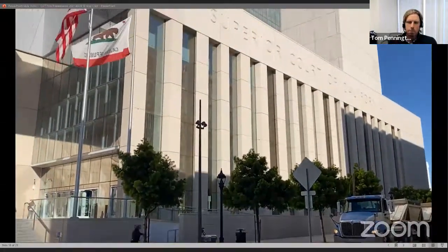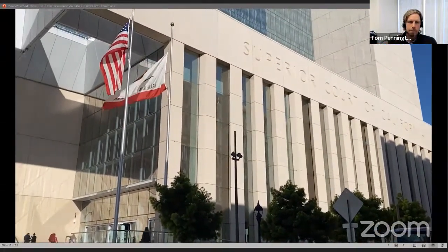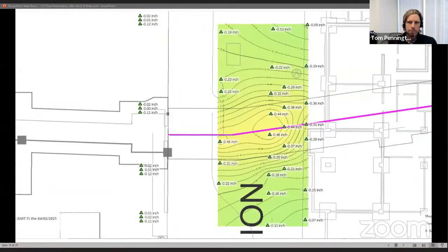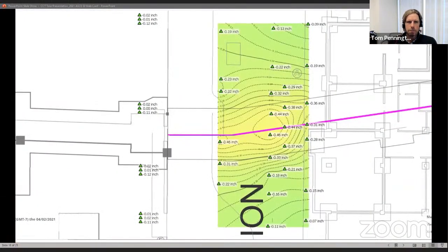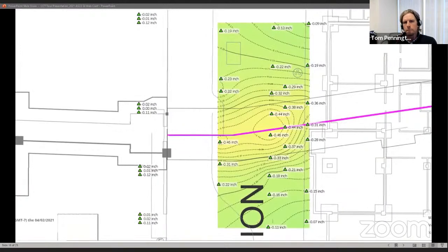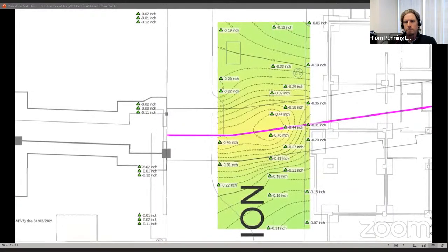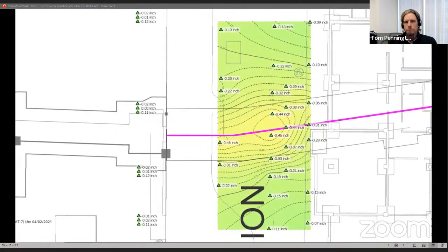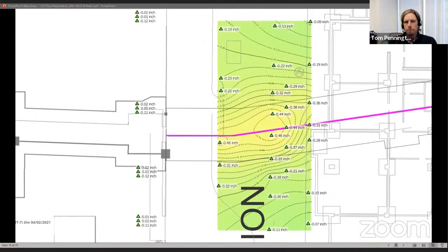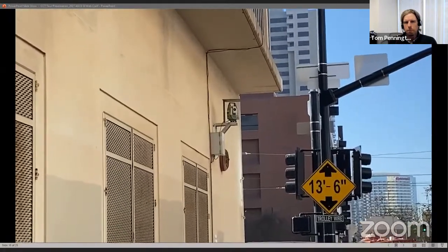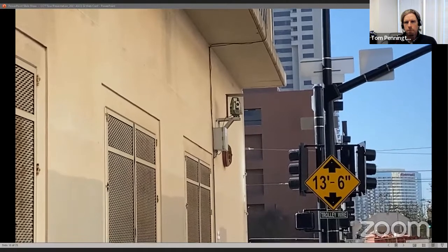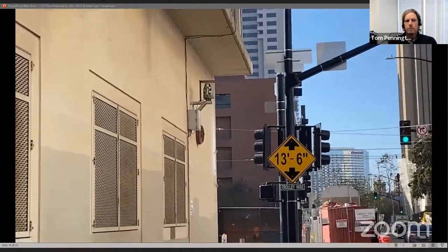To keep a close eye on the impacts of tunnel construction, a suite of geotechnical instrumentation was put in place to monitor movements in real time. Automatic total stations were used to continuously monitor installed prisms to measure locations of utilities, road services, building targets, and the tops of anchors set deep into the ground immediately above the tunnel.